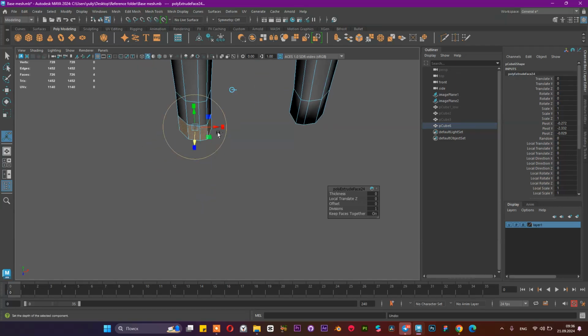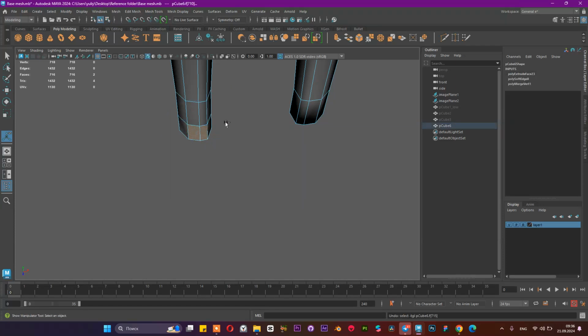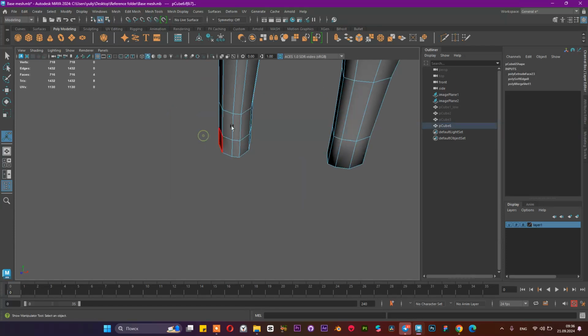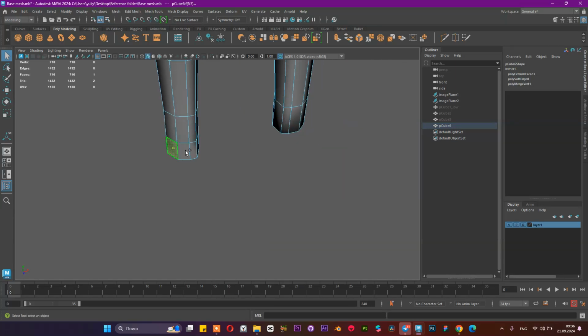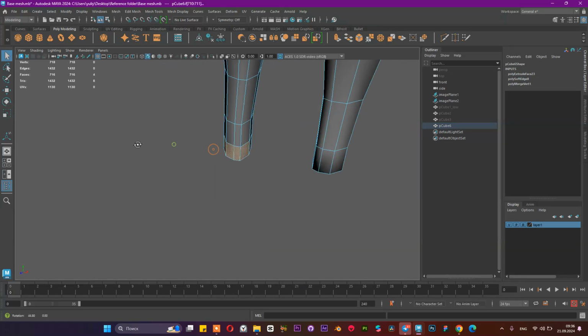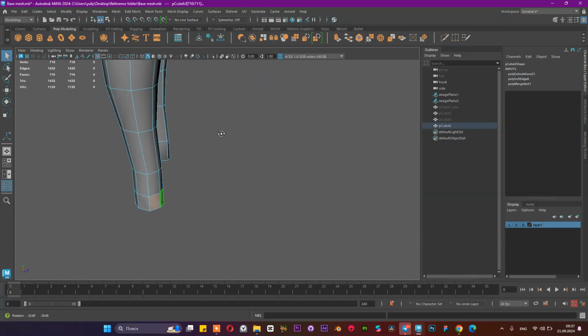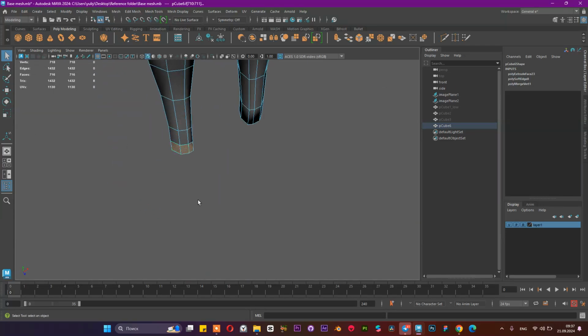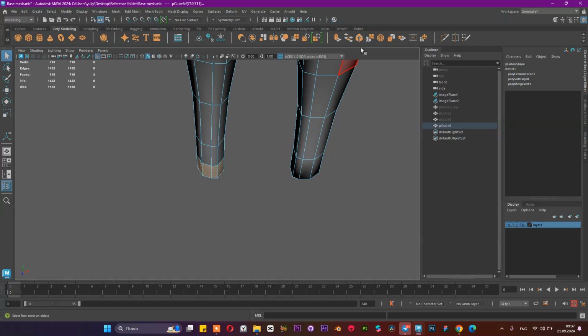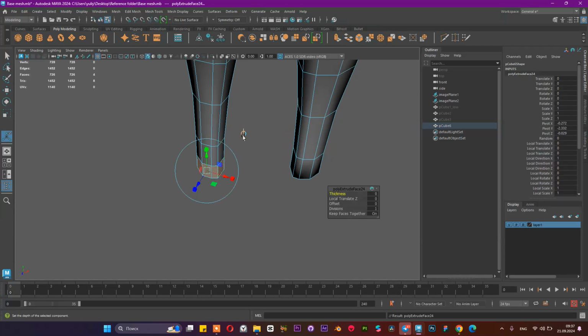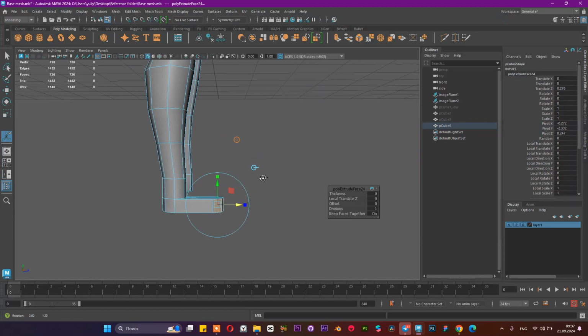For the extrusion, you can switch between positions of this manipulator. For example, let's do it again. Select vertices. I'm selecting four, and I'm going to scale it further. Let's select extrude, change the position of the manipulator, and move it further. Now we have some feet.